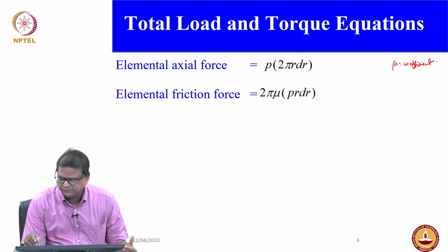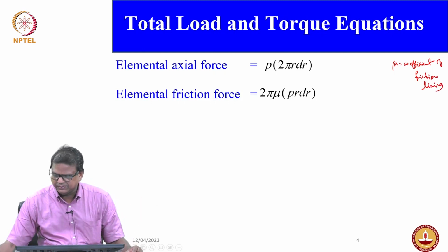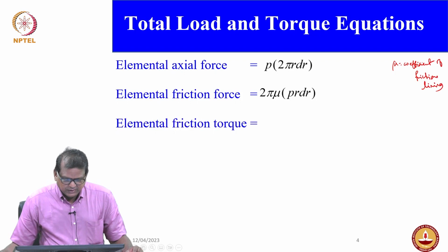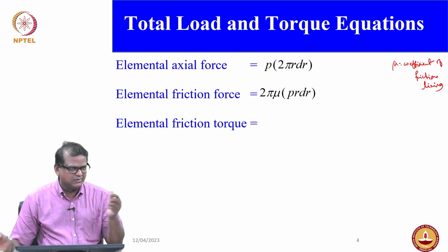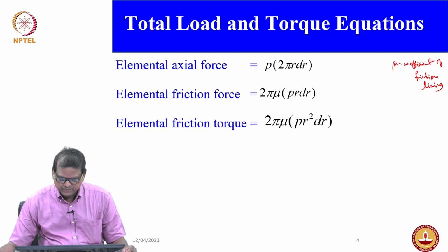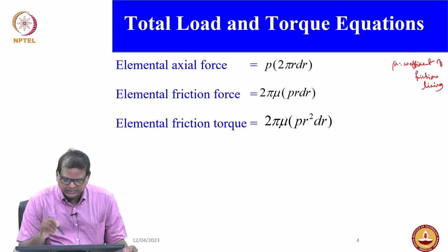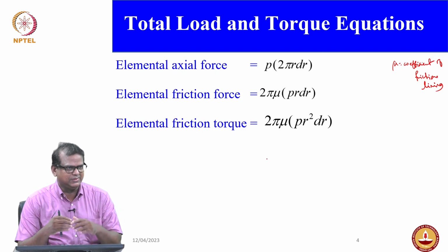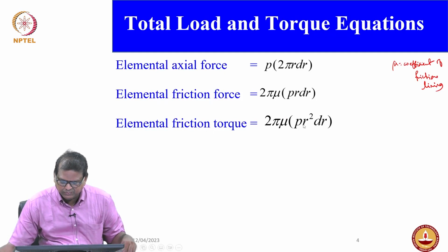That is what helps to transfer the torque through the frictional arrangement. Now, the frictional torque would be the frictional force into distance, which is small r. And in this we are assuming that the coefficient of friction is constant, not variable with temperature, and pi is also constant, only the variable would be p, r square and the dr element.